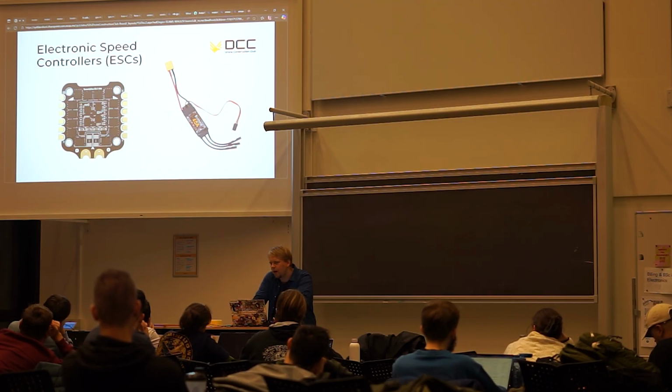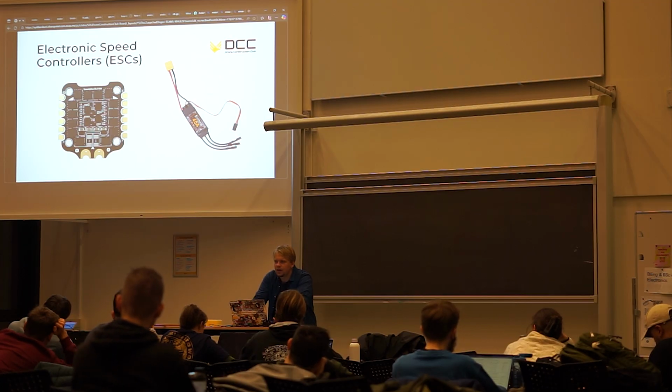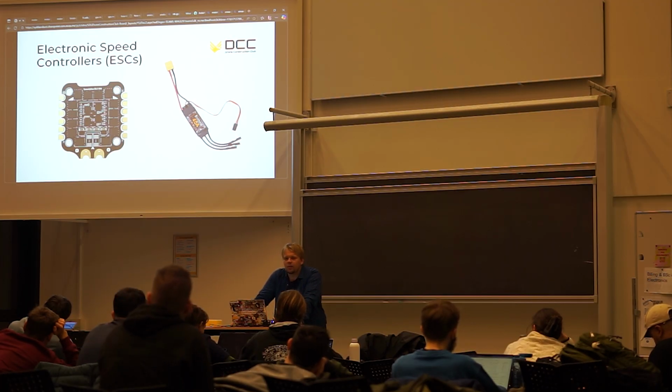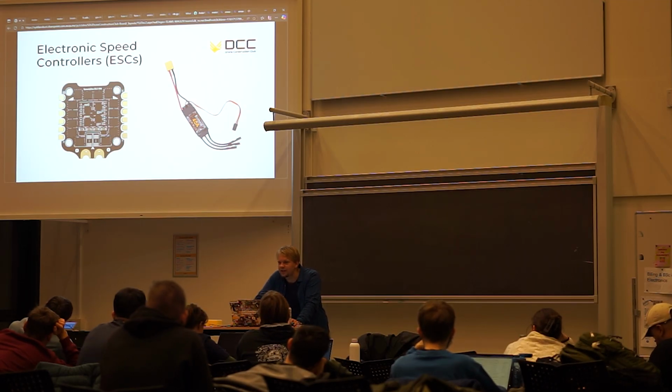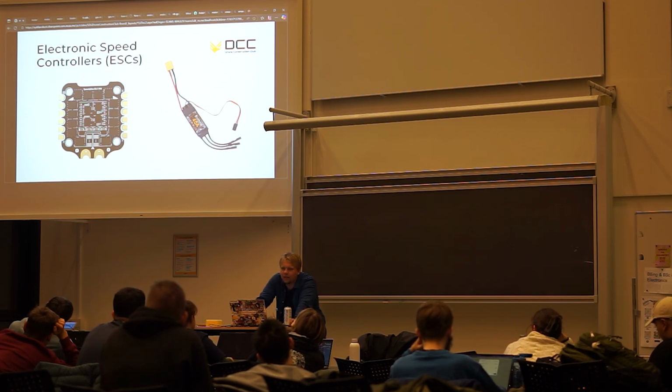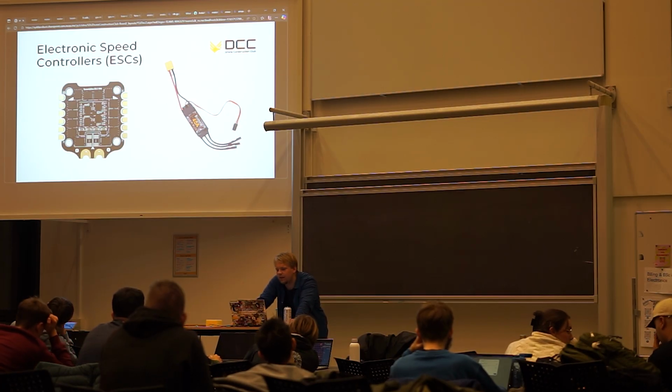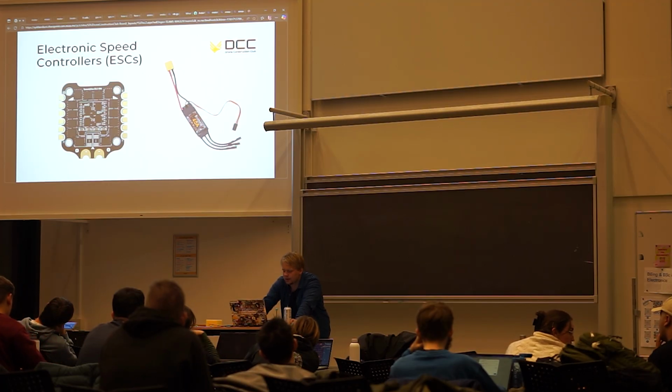Then you have microcontrollers for controlling the MOSFETs, and then you also have the MOSFET drivers. What it does, I don't know. Who understands a little bit of electronics? Do I have to go into what the drivers and MOSFETs are? Everybody understands what a MOSFET is? Nice. Nobody understands. Basically, you have the microcontroller telling the MOSFET driver when to switch, and the MOSFET driver can supply a bit more quickly and does the switching for the MOSFETs.